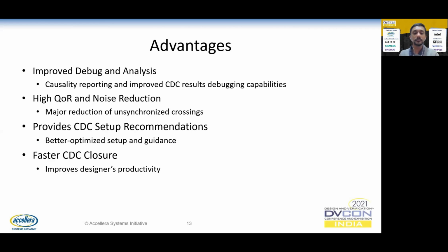We see a setup recommendation by the CDC data mining techniques. This helps in the cleanup of designs with a better optimized setup and achieves expected results. It helps in faster CDC closure, improves the designer's productivity, and reduces the CDC analysis time and effort. It helps review the root causes based on the order of impact on the CDC violations and take action for the bulk resolution.